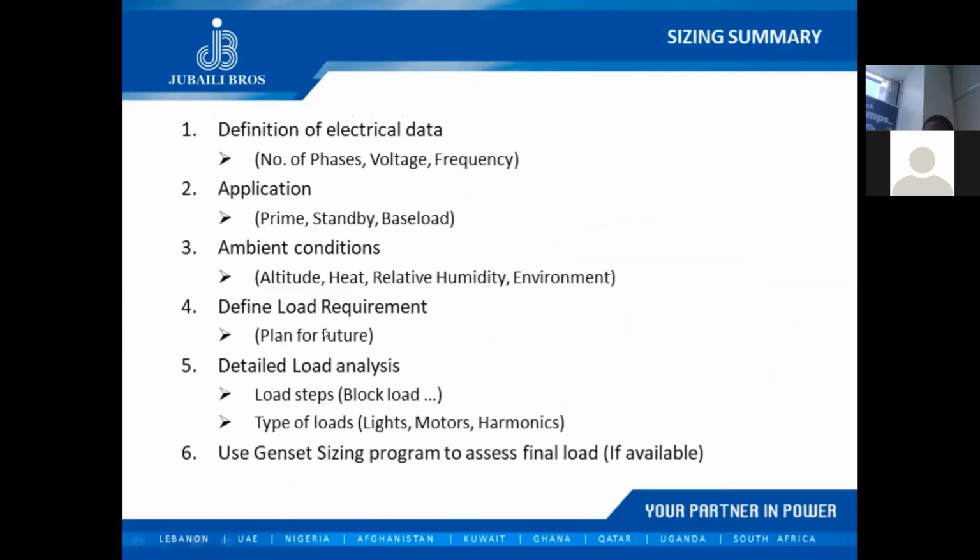Okay, guys, so just to wrap up, we've talked about number of phases, voltages, frequency. That's the most basic questions to ask when we size a genset to be able to select the proper engine and the alternator. We've talked about different applications: prime, standby, and base load or continuous load.